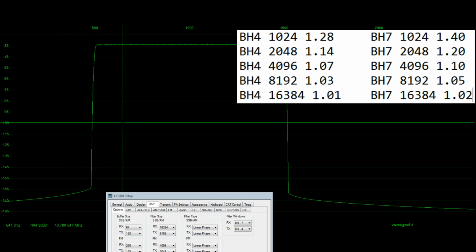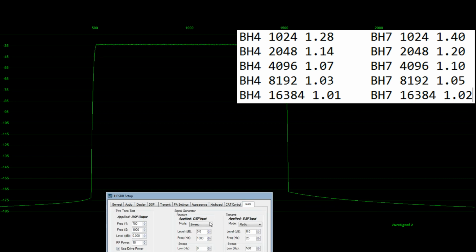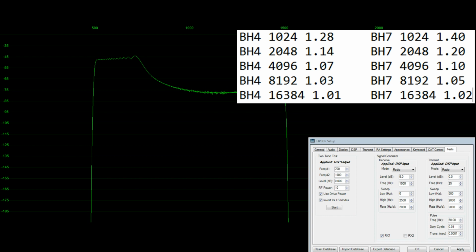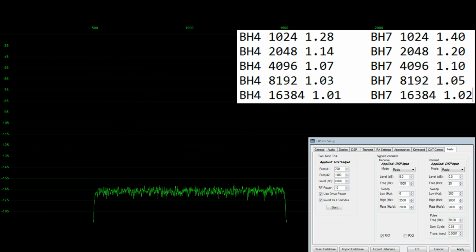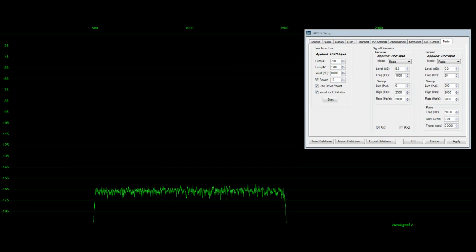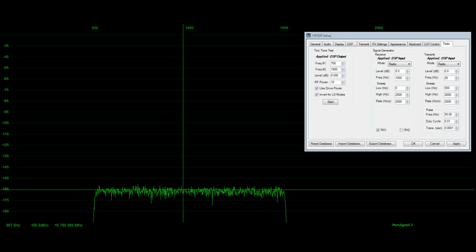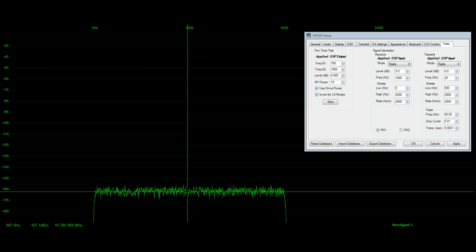So pretty interesting stuff. Well, the next thing I want to do is look at some of the receiver noise floor characteristics, and we'll go back to the test tab now, and we'll take the sweep and we'll go back to radio, which will turn this off. I'll move this out of the way. Okay, so now what we're seeing here is something a little bit different. We're seeing what the software is interpreting as the average displayed noise floor looking in the spectrum now.